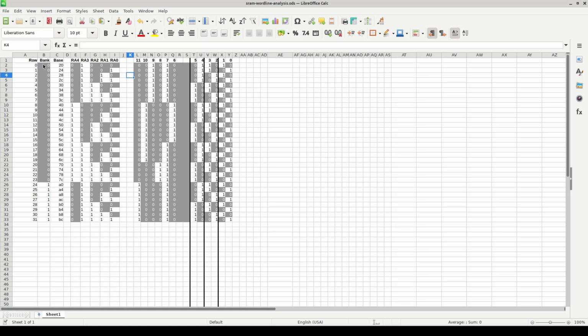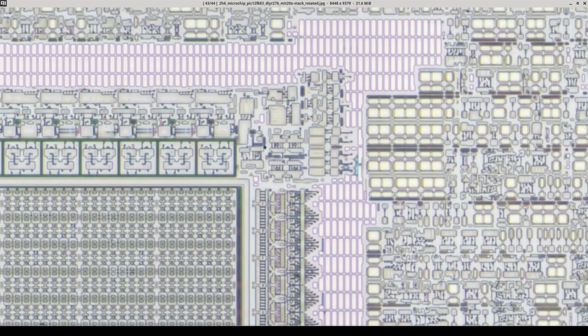We've got the bank ID bit here. That matches perfectly with the bank ID here. And everything up here is essentially just this converted to differential, but also ANDed with bank address equals 0 so that we don't alias with the stuff in bank 1. And then jumping back here, now we can see some of this other. So if you recall, we only actually traced out these first couple of inverters. And so now we know what all this other logic is doing. That's essentially the single-ended to differential conversion for all the other address bits, as well as the ANDing with the bank ID equals 0. And then presumably some of this is responsible for driving the column address as well.